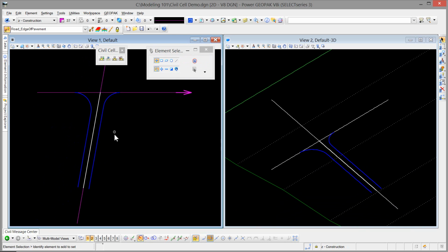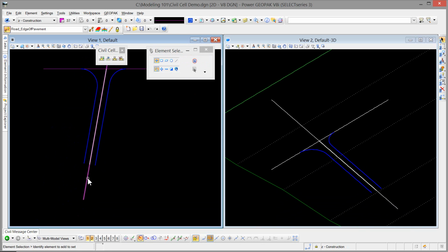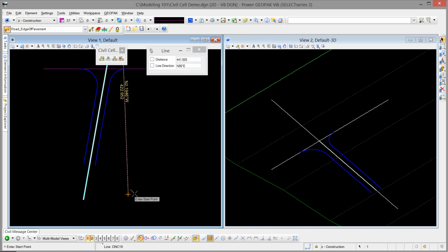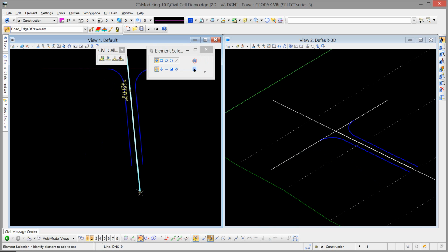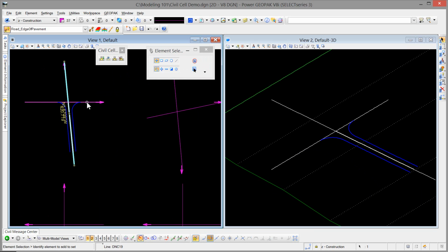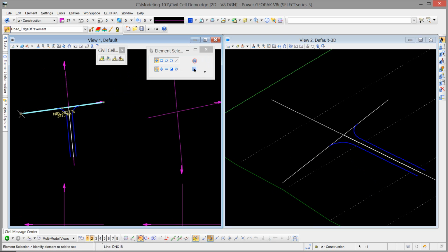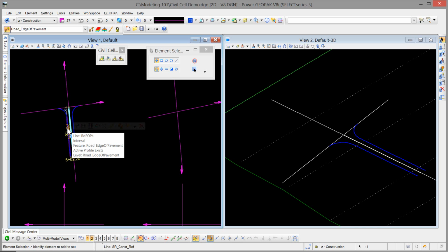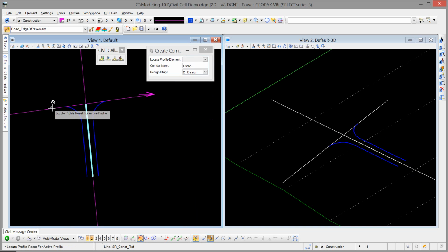And it's always a good thing to test. I've added new geometry. I've got the profile set. So if I come over here and move this around, I should see all of that update. If I move my through road edge, doesn't matter which end I pick here, I should see all of that update. And so everything looks like it's working perfectly. Extensions should not matter here because we've locked in our length here of 200. And I'm just going to go ahead and bump that down a little bit. Let's change it to 150. And you can see everything's working well.